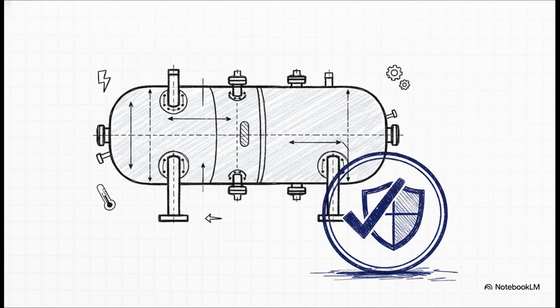And these exact stress-strain principles directly drive the rigorous safety codes used in global manufacturing. The properties we've been talking about dictate the allowable stress values in ASME Section 8 for pressure vessels, they ensure welders are fully qualified under ASME Section 9, and they require standardized testing through ASTM E8. The curve isn't just a theory, it is the fundamental rulebook that keeps industrial equipment from failing catastrophically.